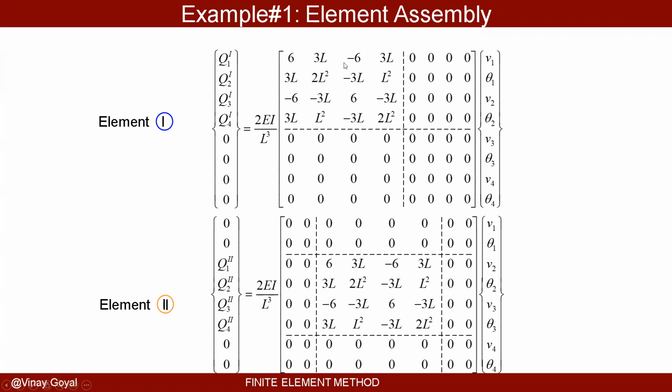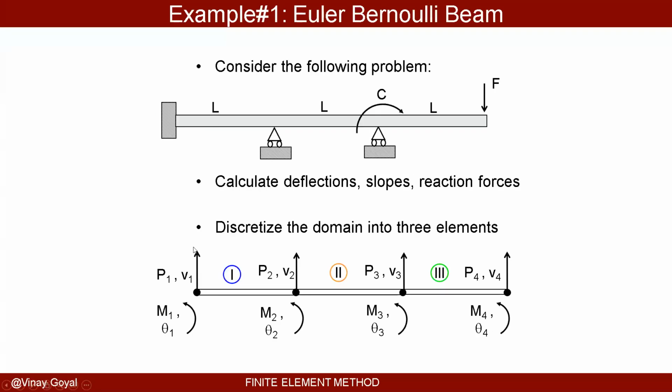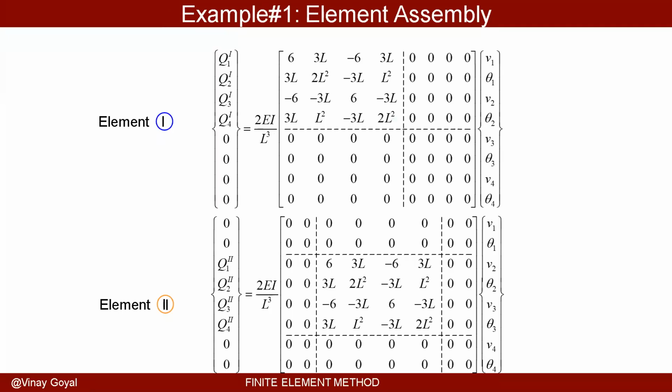So this is one way to do element assembly, by the way. You can expand the whole matrix so it looks this way. Let's look. So how many nodes do I have? I have 1, 2, 3, 4. And there's 2 degrees of freedom per node. In my book, I do it a little bit differently, and I provide the codes that you can write in MATLAB so you can solve the problems quicker. But I should have an 8x8 for a 3 element.